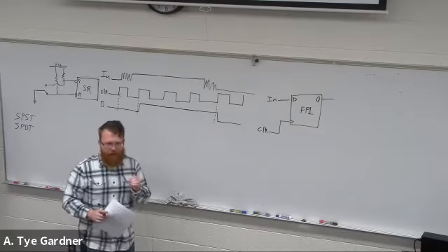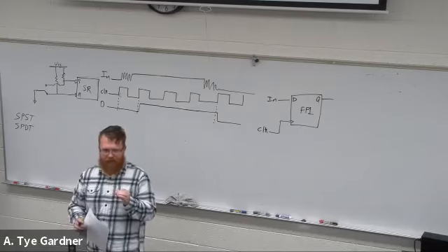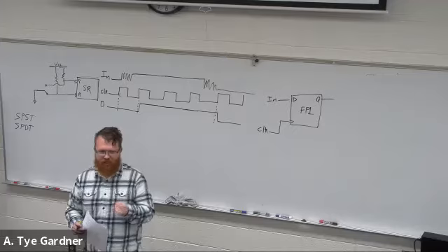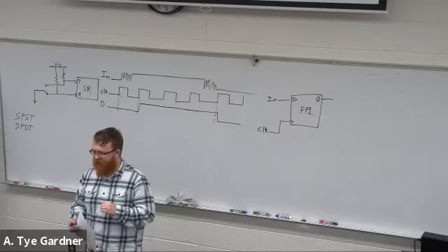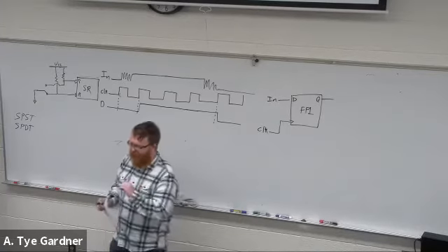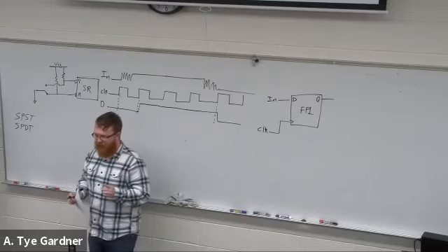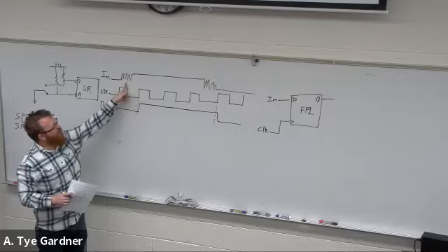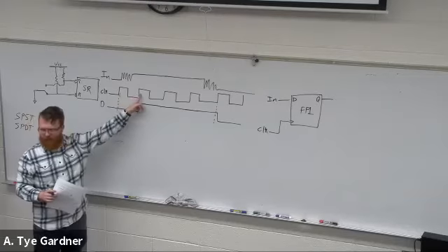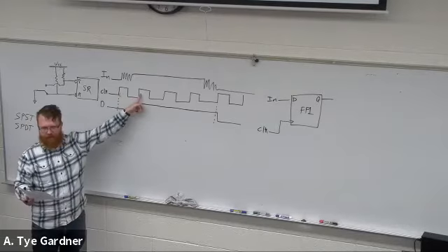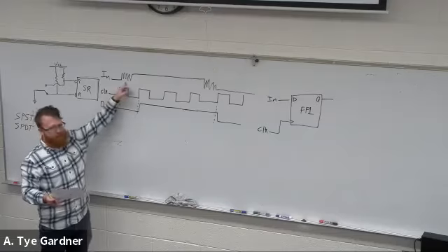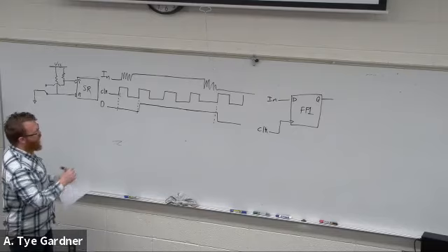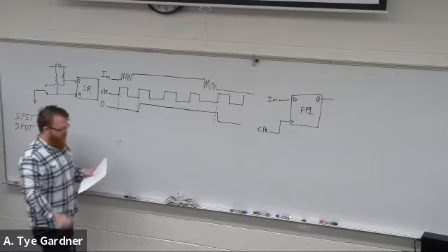Now, the probability of that is super small. You have to be within less than a propagation delay of the rising edge. So the probability of this happening is very small, but it is a real possibility. So you throw it here, you don't really know what it is. That's okay technically, because then you're still going to be delayed 1 clock cycle and you'll update, right? So it is an issue to update in the middle. The worse issue is that you might oscillate. Both of those can happen. Fortunately for us, there is a really nice and easy solution.